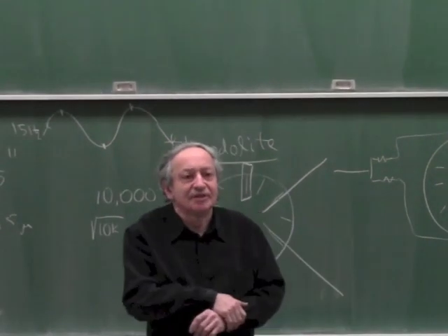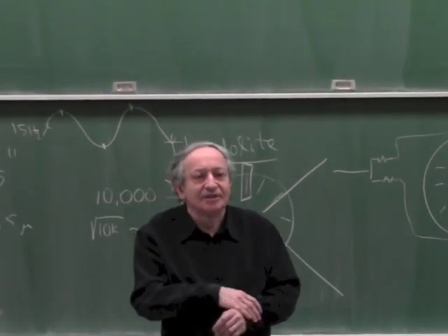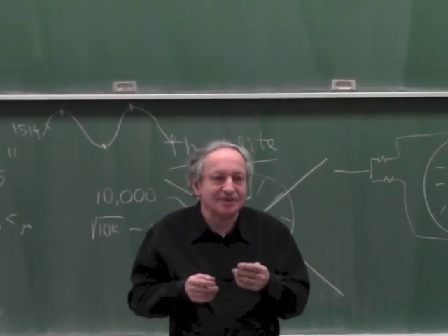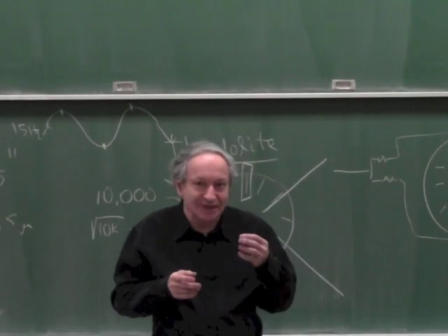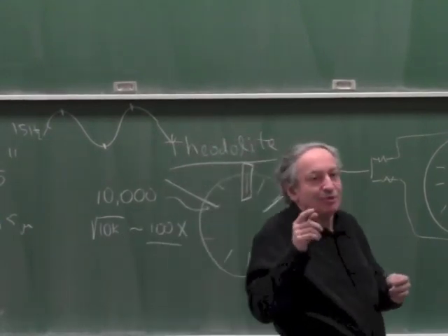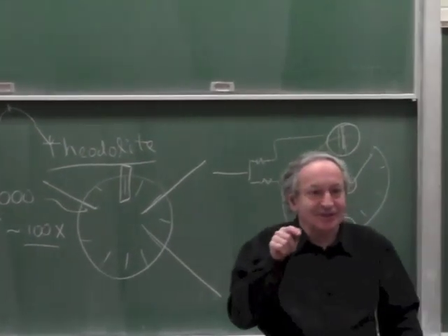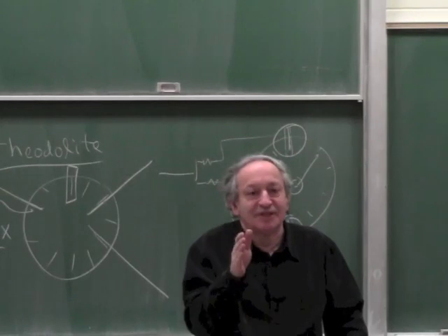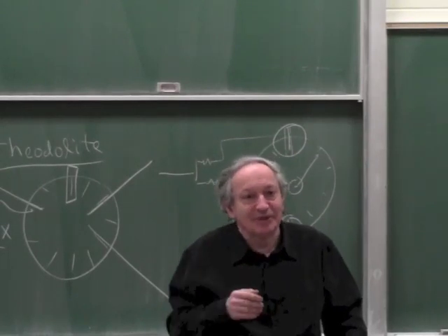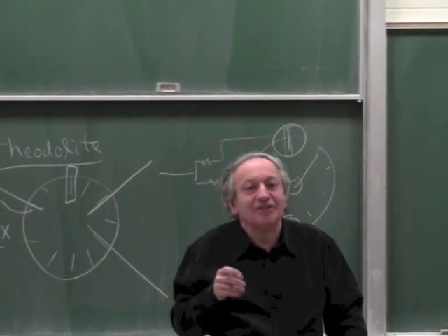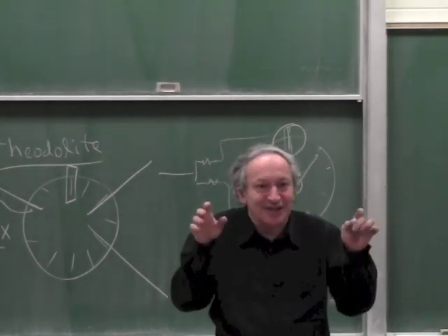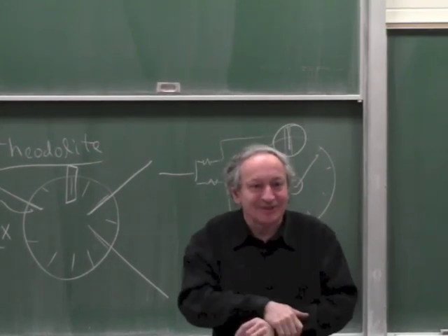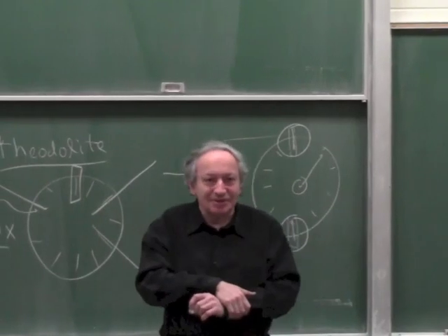Yes, please. Could you use multiple cameras to phase shift it to capture? Yes, but then they have to be registered to one another. You can always do some parallel shifting because you can control the sample point in a camera by the trigger. So you can have 10 cameras, each one at 15 Hertz bandwidth, but each one shifted a tenth of a cycle. And then you will get 10 times the bandwidth, but it's still only 150 Hertz. And you have to register the 10 cameras so the images align. Otherwise, when you jump from camera to camera, it appears the object is jumping. So it's problematic. It can be done, but it's not worth it.